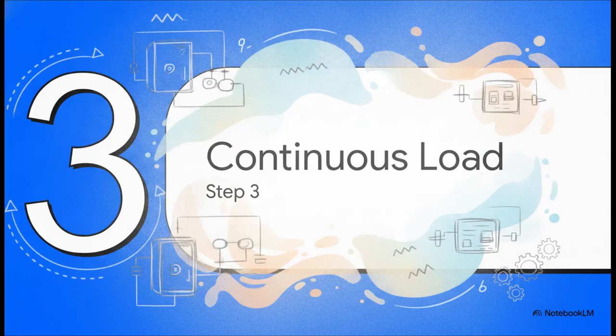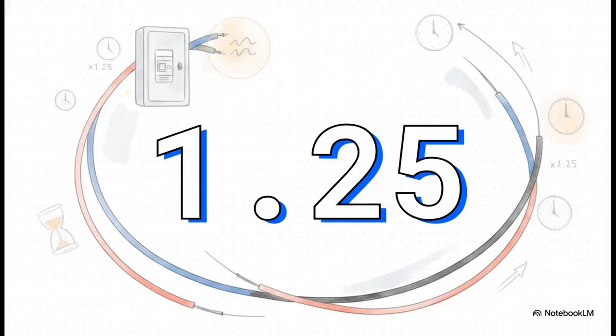Moving on to Section 3, the Continuous Load Penalty. Now that we know which column to look at, let's look at the first specific mathematical penalty conductors face in the field. Remember that 3-hour mark? Per Section 210.19(A)(1), where a branch circuit supplies continuous loads, we have to multiply that continuous load by 1.25. That is a 125% penalty just for leaving the equipment on for 3 hours.